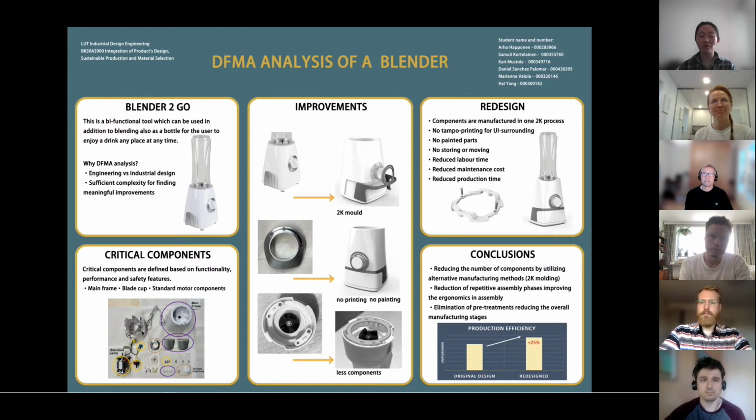In the cutter head, two separate holding components were replaced with a single component, and at the same time, the number of screws used for fixing were reduced by two screws. Reducing the number of components reduced the assembly time, provided cost savings in tooling and logistics costs, and reduced the number of required assembly directions.